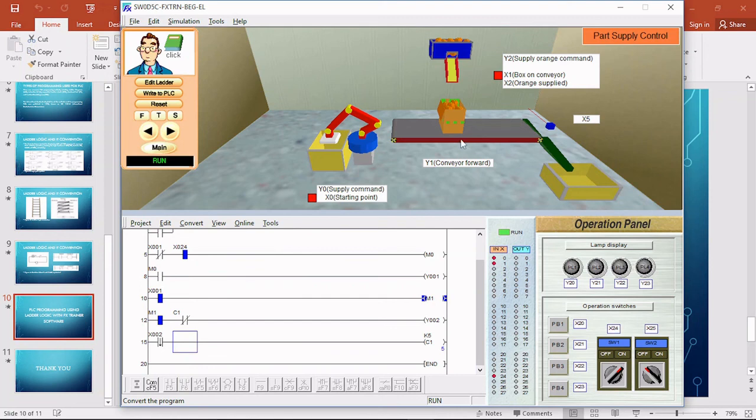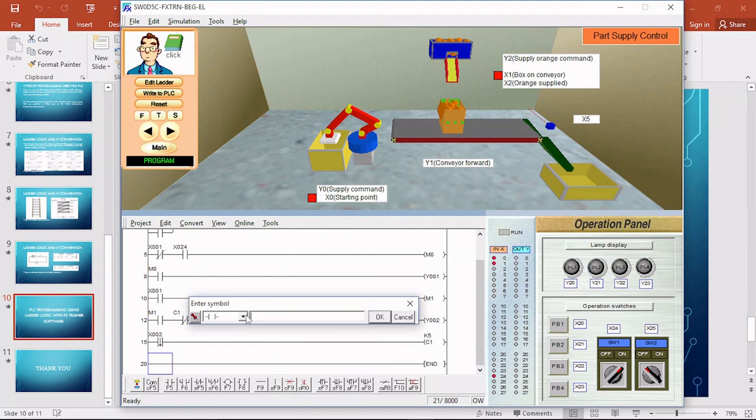However, we also need to have some kind of output that we can control, so that once the box has been dropped here, the latch that we're using to start back the conveyor should go on to be de-energized, so that the conveyor will not keep running repeatedly. So in that case, we could just edit this,